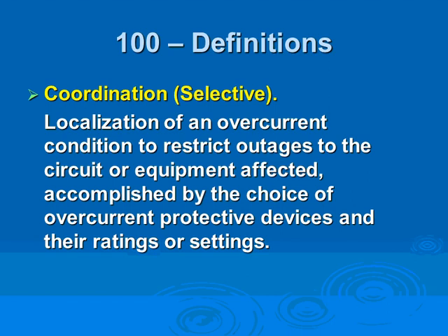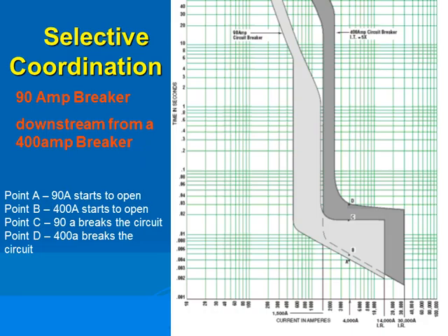That's what overcurrent protection coordination is. It assures you that if you have a short circuit or ground fault in one section of your power system, that particular section is the only one that will be disconnected. Everything else will continue to operate properly. It's required for hospitals and a lot of places; all the engineering projects that we did must have an overcurrent protection coordination. I'll show you this in a second. This is how the overcurrent protection devices look.